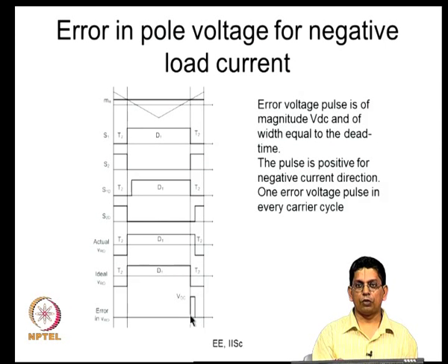You have to do it from the point of view of protection. Once you do it, that has an influence on the average pole voltage. It shifts certain transitions, either the low to high transitions or the high to low transitions, depending on the direction of the current. It is just shifting the instant at which the pole voltage shifts, and that leads to a certain error.